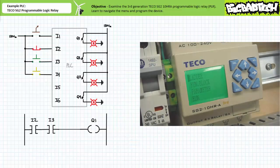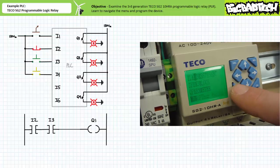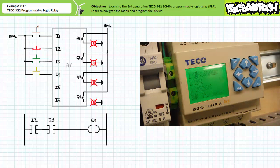Let's run this program and see how the PLC responds to these 4 different scenarios. Navigate to Run and press OK to place the program in run mode. The device asks us to confirm our selection. Navigate to Yes and press OK. Press Escape to return to the home screen.